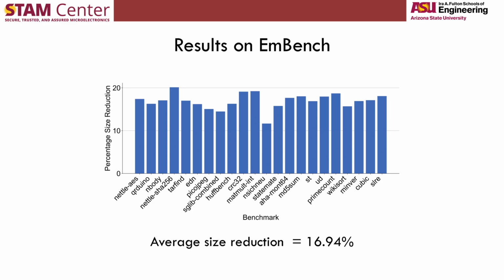So on executing these benchmarks on the EMBench suite, we're able to get an average size reduction of about 16.94% after we translate the uncompressed instructions to their compressed format.